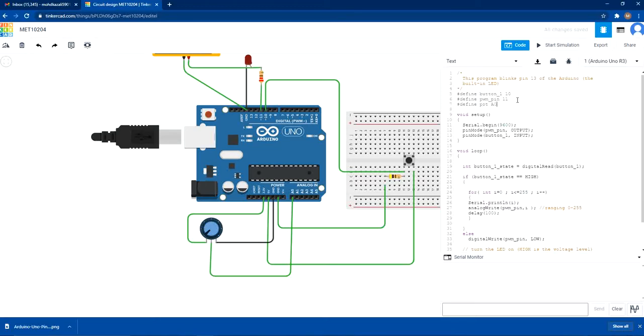The pin will be A0 because this is the analog pin that we use in the hardware setting. Once we select that, we can straight away read the digital value from the pin A0.